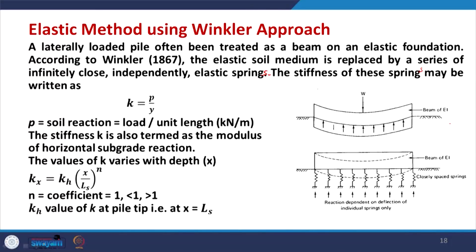So, basically the stiffness of these springs is written as K equal to P by y, P divided by y. So, what will be the soil reaction? Soil reaction is load per unit length, that is in kilonewton per meter.